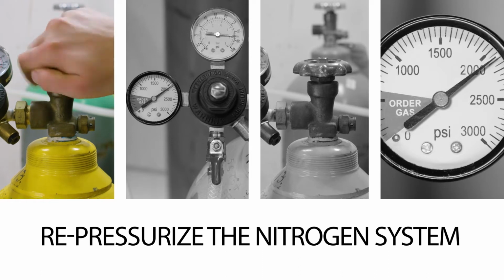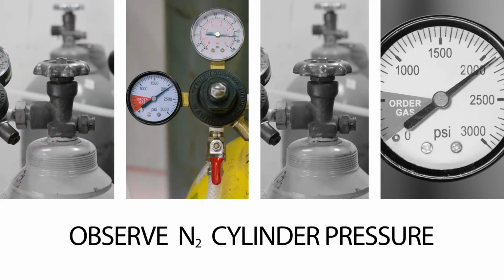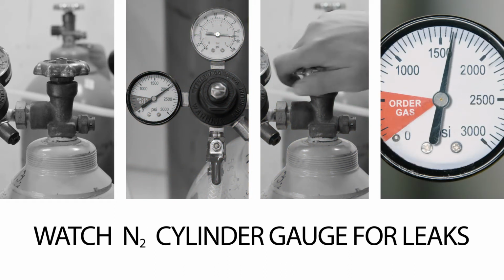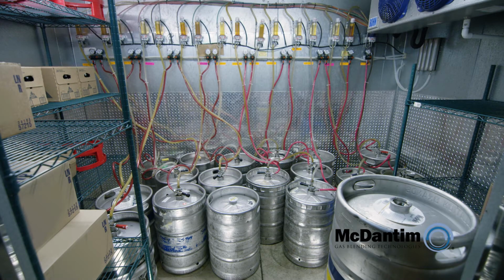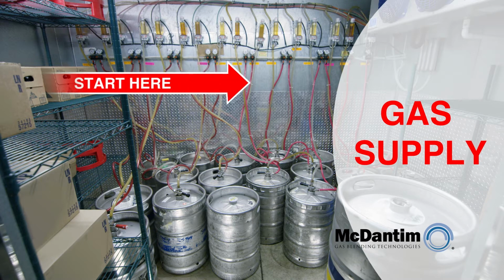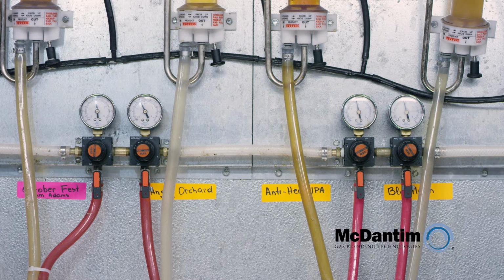Now let's repeat the test on individual regulator banks and regulators. Again, don't forget to repressurize the nitrogen cylinder and follow the same 4 steps as you've done before. Now, start at the regulator furthest from the gas supply and open its ball valve. Generally, when diagnosing jumper coupler leaks supplied by banks of regulators or single regulators within a bank, it is best to start at the end of the line and work your way towards the gas supply.